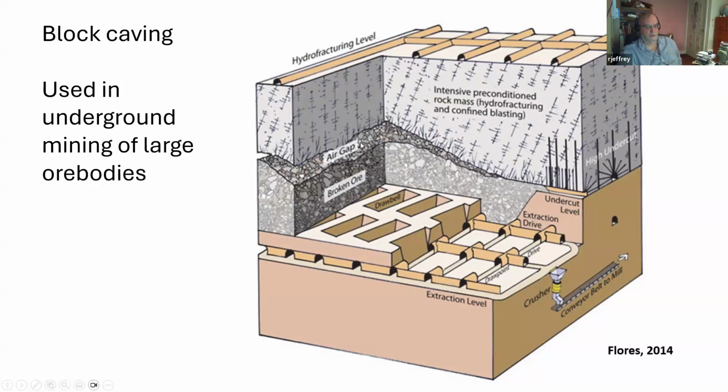However, those weaker ore bodies have mostly been mined, so a lot of the newer ore bodies have stronger ore that requires something to be done to it in order to weaken it. And that something is place hydraulic fractures into it in many cases. So here they developed a system of tunnels to allow drilling of the boreholes and then placement of the hydraulic fractures.